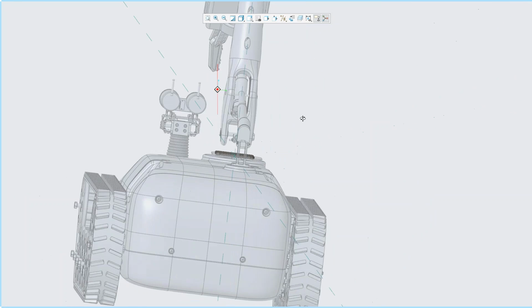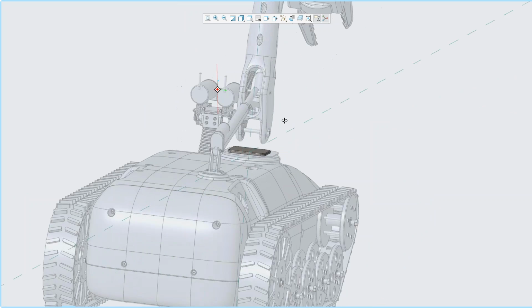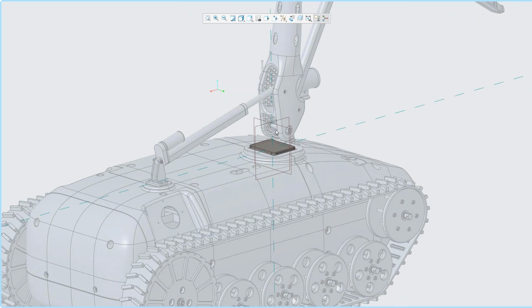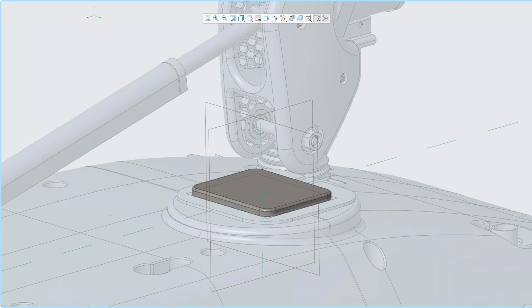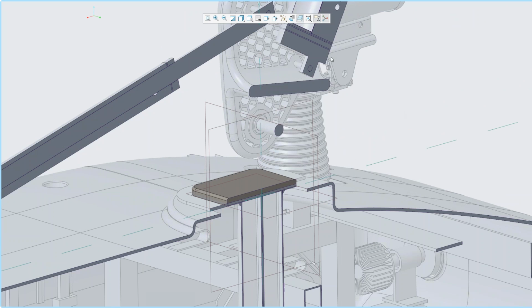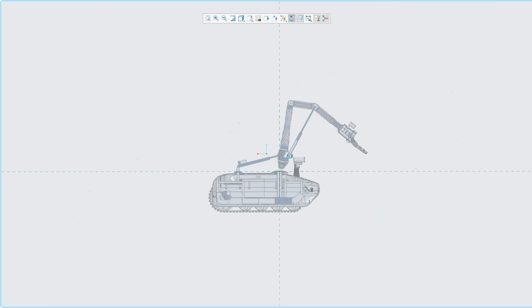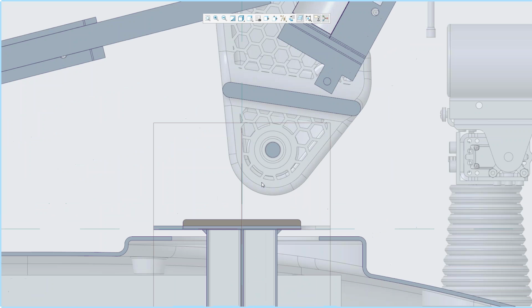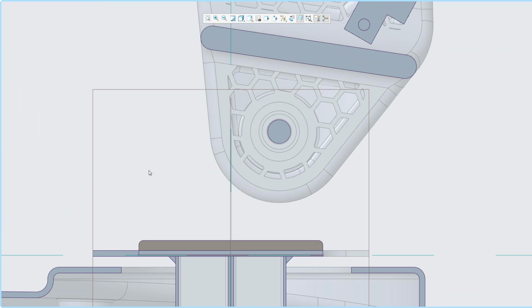Now I'm working within an assembly building a part, and it's kind of in the middle of my assembly, so I might get a little confused here. What I can do is clip the model directly to that sketch plane and then work off of it that way. So clipping is now new in Creo 4, and now I can start working mostly off of my right mouse button. So I have sketch tools embedded in here, and I can start sketching.